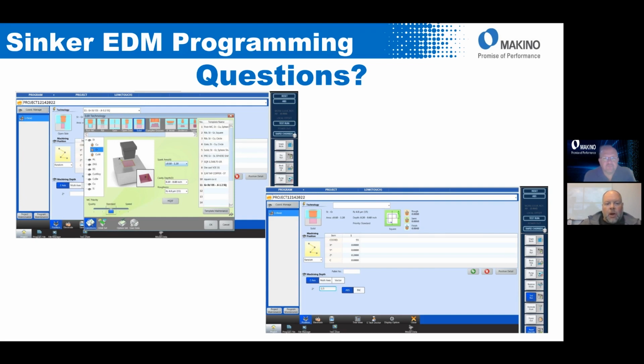Adaptive control, though, really all of the Makino sinkers have adaptive control. It's what's going to actually make those adjustments on the fly better generally than the operator can, because it monitors the spark constantly and it's adjusting. So its first line of defense is to add off time to stabilize that. Once it adds off time and stabilizes, then it starts to take that on time and put it back in. And then also that off time adjustment back where it belongs.